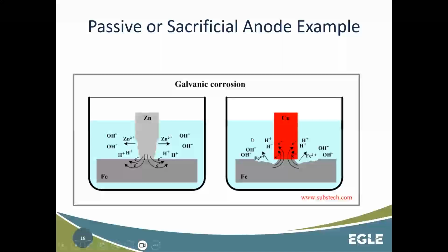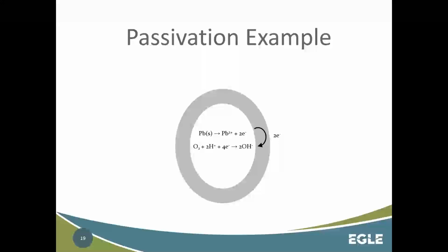All right. So again, driving into this passivation concept, where we're essentially creating that liner, or surface, if you will, with this pipe material. If you remember from one of the first slides in this presentation, we were looking at this exact equation where you have a lead pipe, solid lead. Solid lead goes into one reaction, you have that electron driving off, you have the lead material itself driving off into the water, and this is your equation with water as well. Okay, so you're losing that lead in this situation.